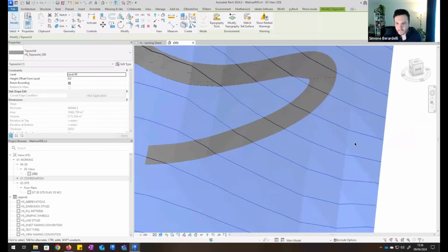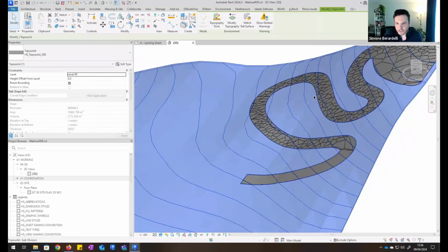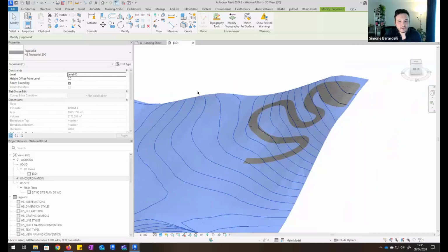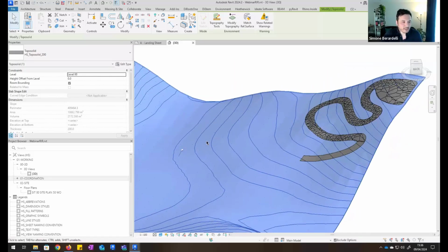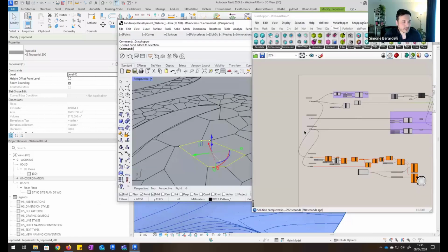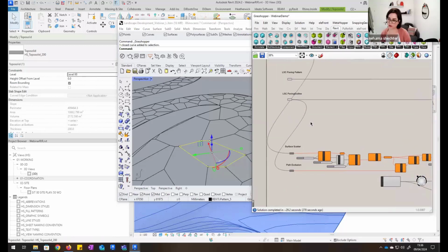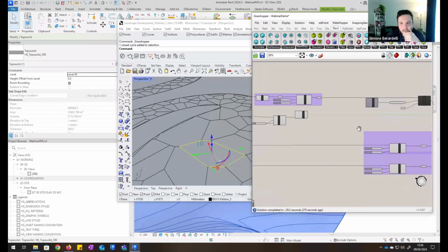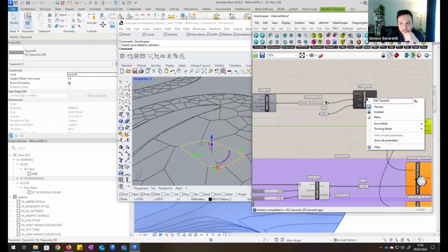You can see all of the triangles in here are the meshes of the surface. But I need to keep this in Rhino Inside for now because we're gonna scatter some trees on top of it, so I need that reference. But once you modify the toposolid in Revit, it disconnects from the Grasshopper script? Yes, it's kind of disconnecting through all that, but I have the option here.